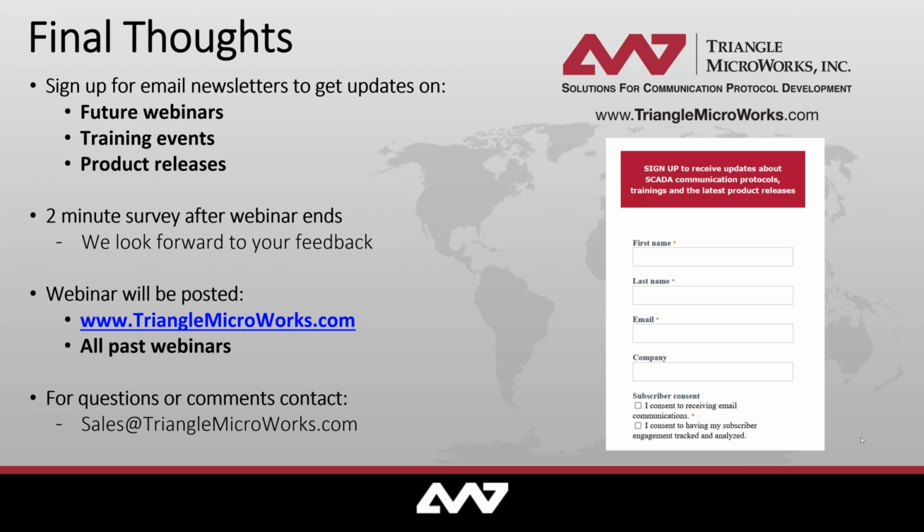Another good question, this might be more for Jackson. Is GOOSE traffic limited to an individual substation? So that's a great question, and it's not a short answer. GOOSE is a layer 2 communication protocol. What that means practically is that it's not able to traverse a router without the use of a VPN or tunnel. So traditionally, I would say GOOSE was kept within a single substation, unless you were to use a VPN or tunnel in order to transmit the messages between them.